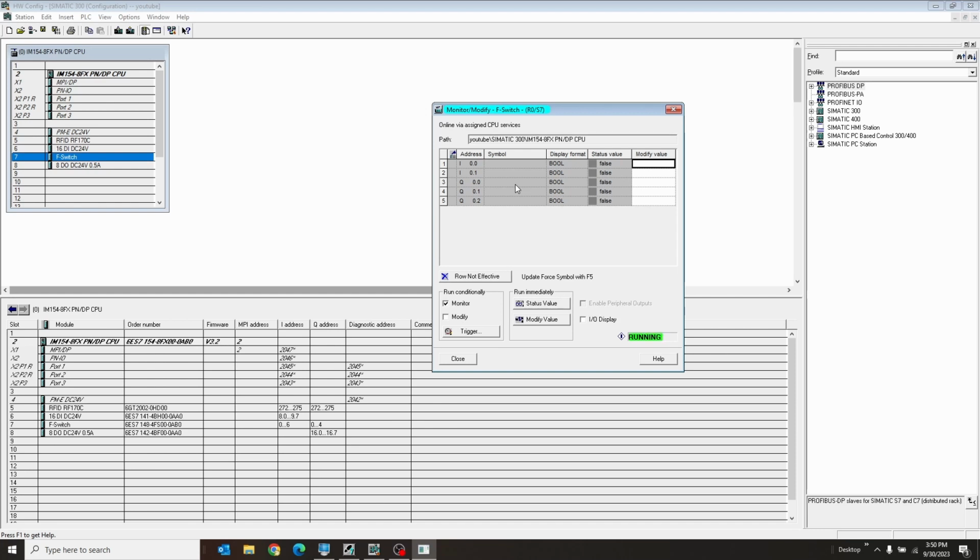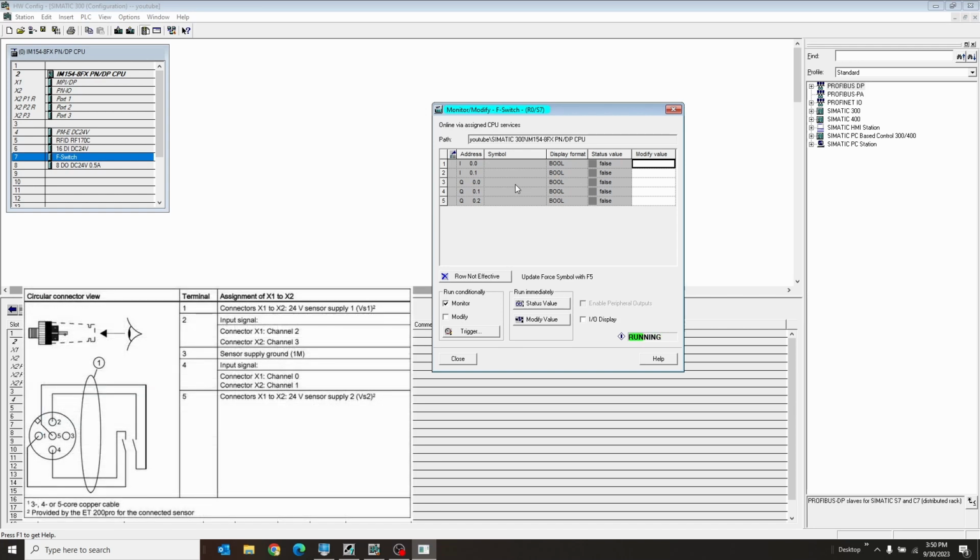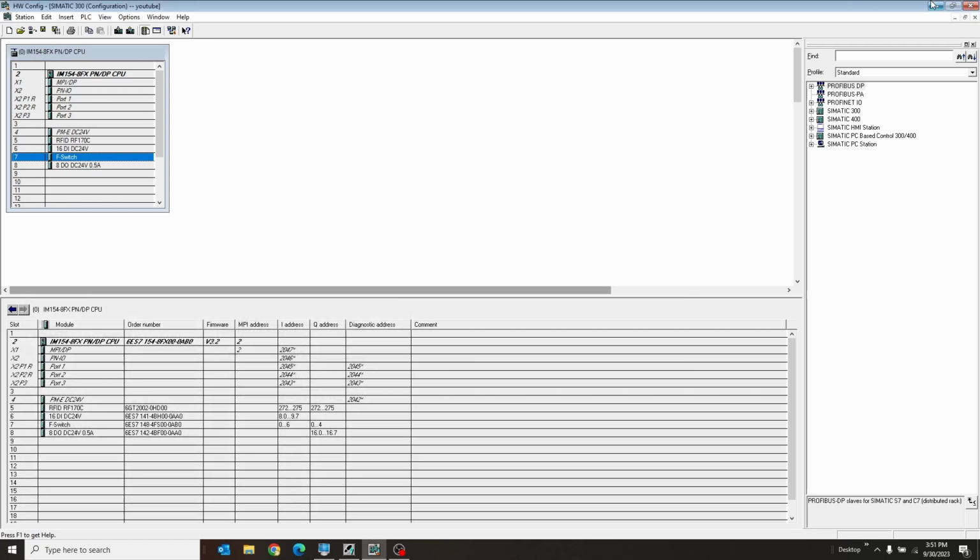I am using a 5-pin wire, and by the way, 5-pin cable has got me before where we have a whole lot of 4-pin around, but the 5 pins are more rare. But because it uses the 5th pin as a safety channel input, it needs to be there, and I've gotten caught with that before, but this has that. So then why isn't my e-stop showing up as good here when it's unpressed? Well, let me show you why.